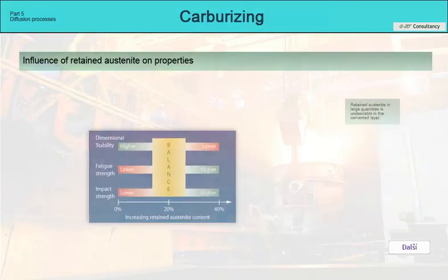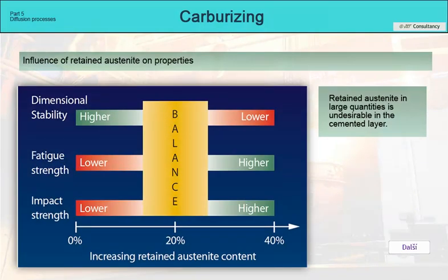In terms of mechanical properties, residual austenite does not always have a negative effect. Due to its properties, such as higher ductility, it can contribute to better low cyclic fatigue strength in some cases. But these are exceptional. Its biggest drawback is that it is not stable and will gradually transform into martensite, although this can be over a long period of time, on the order of weeks.